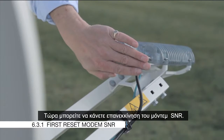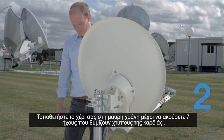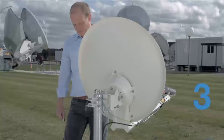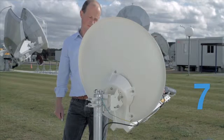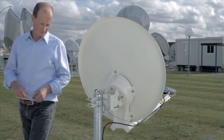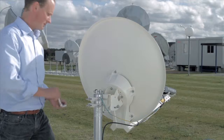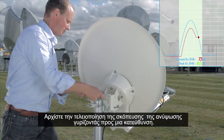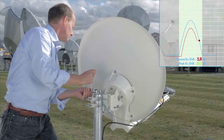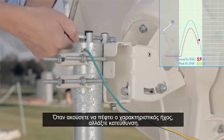Now, reset the modem SNR meter. You do this by placing your hand over the feed horn for 7 heartbeats. You hear the ambulance tone again. Check the azimuth locking nuts are loose. Start fine pointing the azimuth by turning in one direction. When you hear the tone drop, change direction.